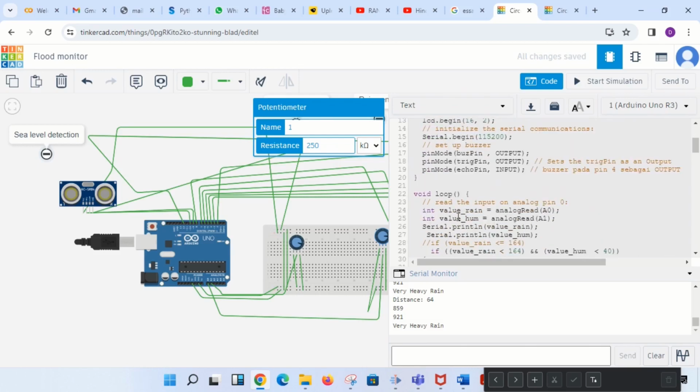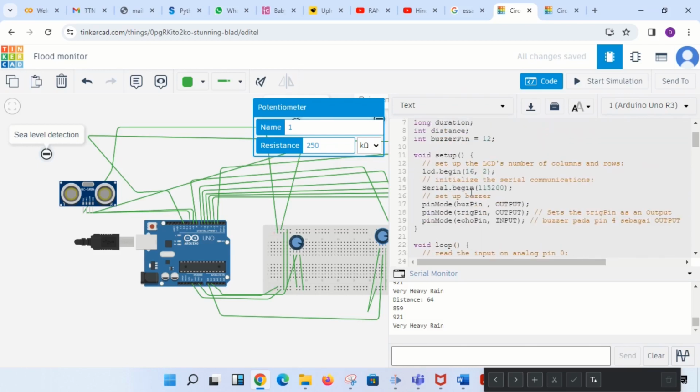Okay, so now I will come to the void setup function. In the void setup function, as all of you know, you write lcd.begin to initialize the LCD, and you have to write Serial.begin, and the pinMode for whichever pins you have discussed. The analog pin is normally not required to be written for the potentiometer. So the buzzer pin, LED pin, trigger and echo are digital pins. I have written which pin is in input configuration mode and which pin is in output configuration mode.